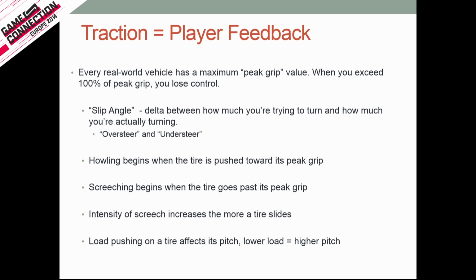So think of it in terms of how much, in percentages of peak grip. When I'm doing tire sounds, I start to think about it. A tire starts to sort of howl, or you get this kind of scrubbing sound, as you approach 100% of peak grip, and then it starts to screech once you go past the peak grip. And then the more you get past that, the more intense that screech gets. It'll start to develop into a howl, and then it'll start to develop into a screech. And tire audio is a key part of players knowing where the edge of grip with their car is.